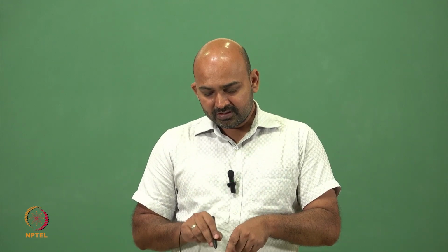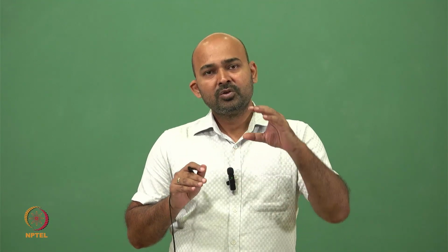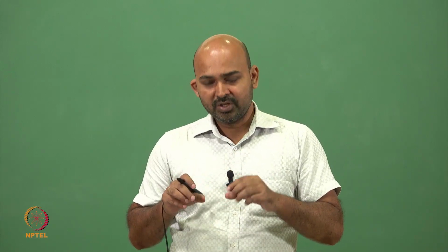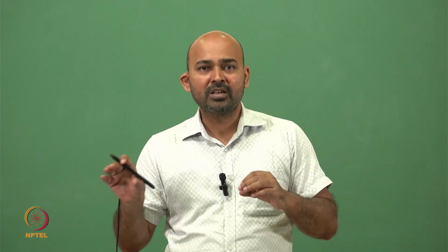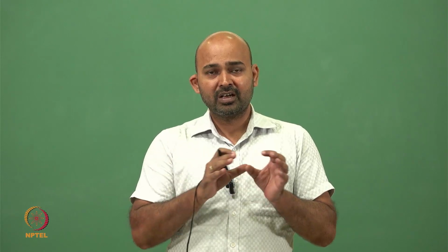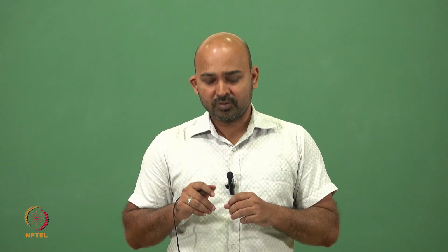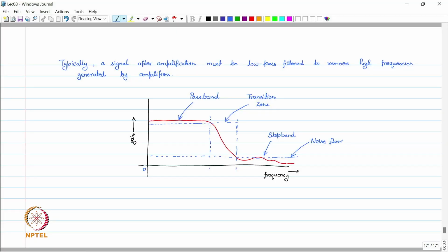However, the filter response is very small at high frequencies, so if high frequencies come in at the filter, they will be suppressed because of the very low gain of this filter, and will not pass through. So this acts as a low pass filter, a high cut filter. High frequencies will be cut down. We can see this by this red filter response: high gain on low frequencies and very low gain on the high frequencies.